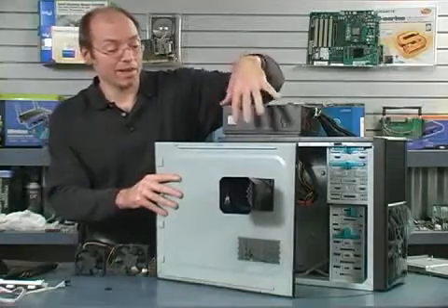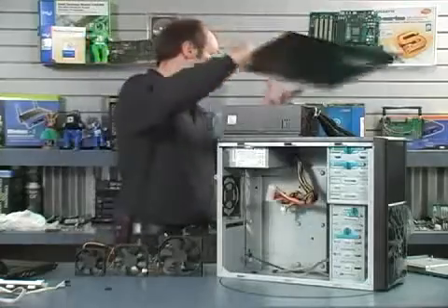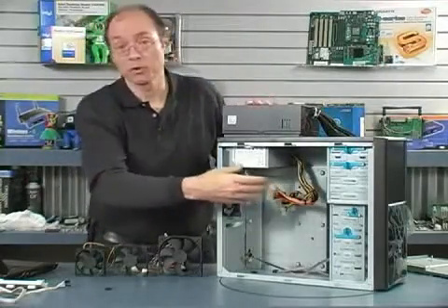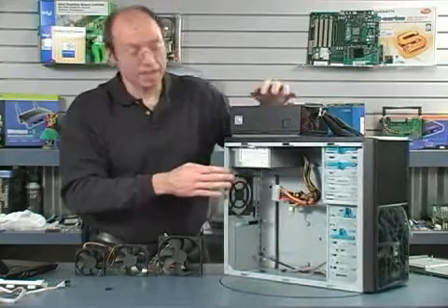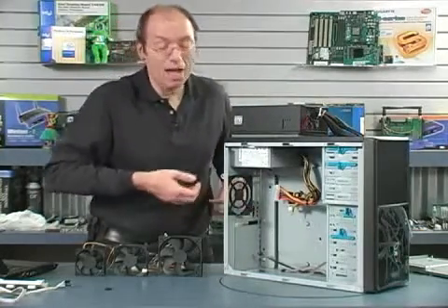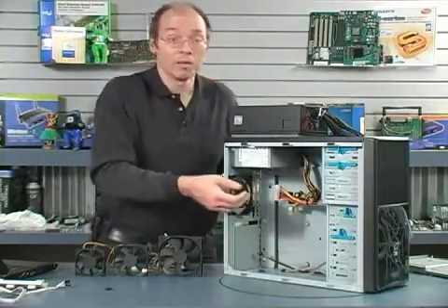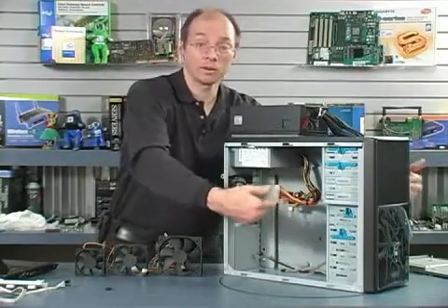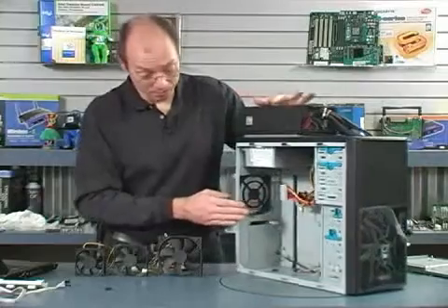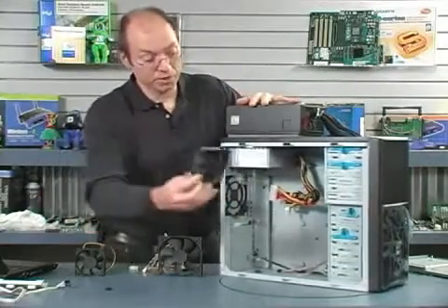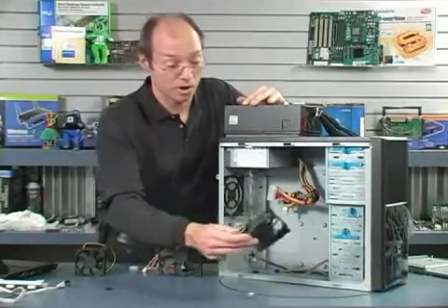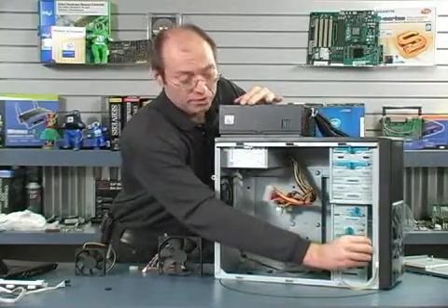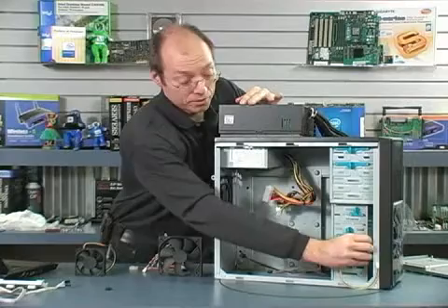See, the idea is that the air inside the case is heated up. So in order to better cool the processor, we want to draw air directly from the outside to cool the processor. So again, that's why we want more air generally coming out than being blown in, because we want to create a suction. We want to create a vacuum so that air is being taken in through the various vents on the system. So again, if I'm going to mount 4 or more hard drives, I'll usually take a 92 millimeter fan and mount it up in the front here so that it'll adequately cool all of those hard drives.